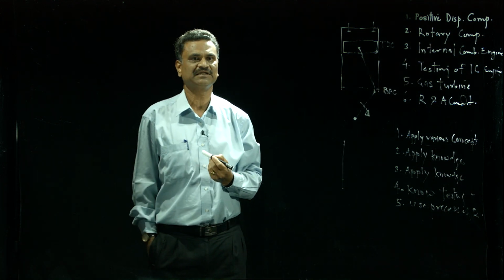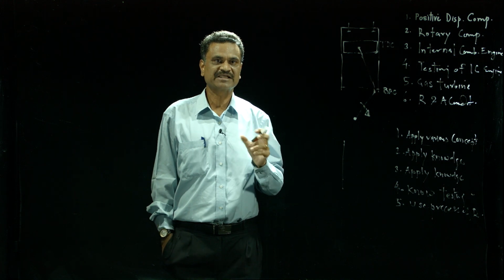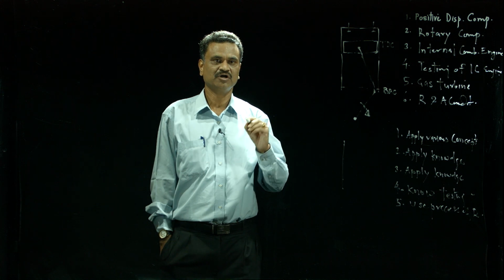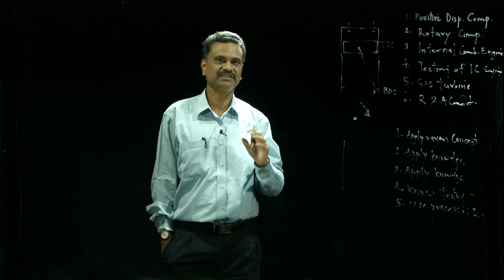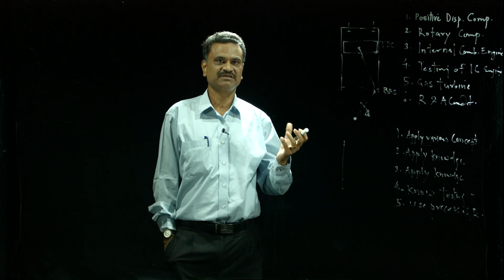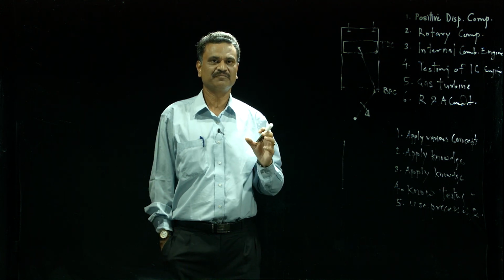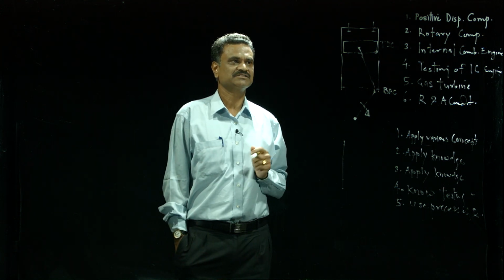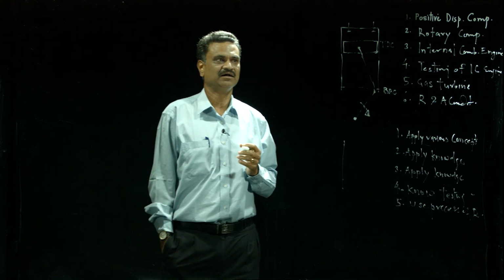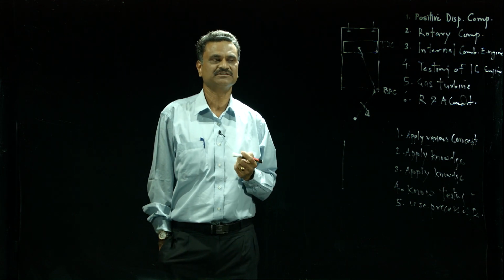Now, the second important unit is the rotary compressor. In a rotary air compressor, compression of air takes place due to the rotary action of the blades. The pressure increases due to rotary action of the blades in the closed chamber. So, at the outlet the pressure will increase, and that depends upon the size, design and type of the compressor. There are various applications, and we select different types of rotary air compressor according to the requirement of the application.